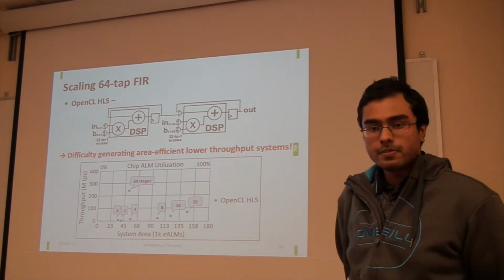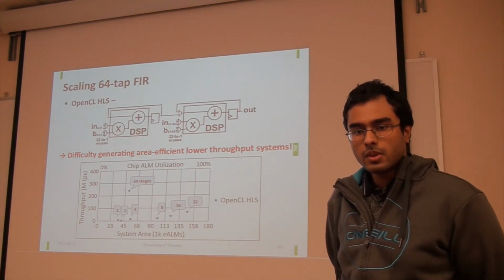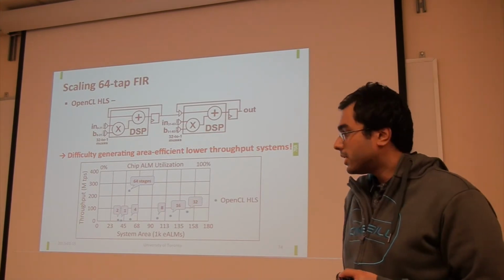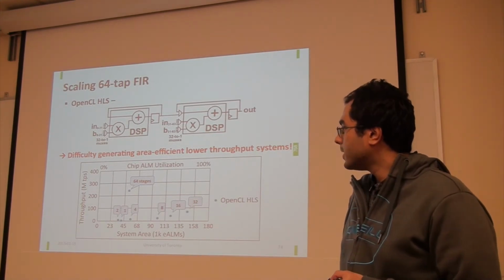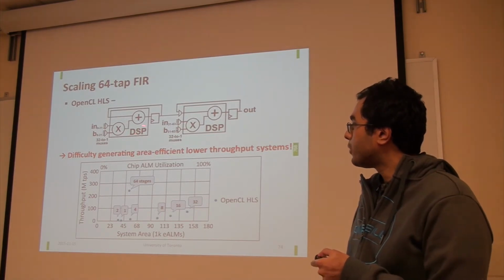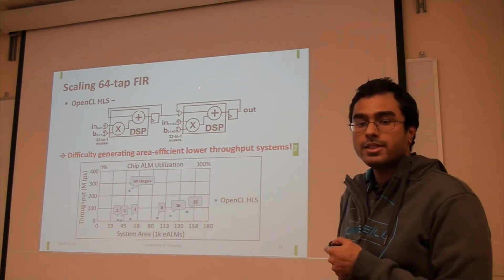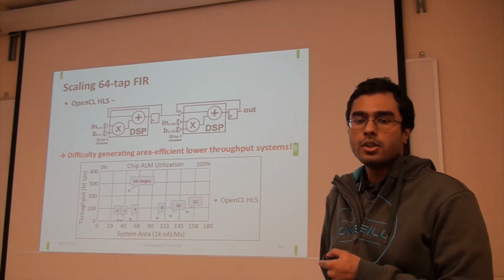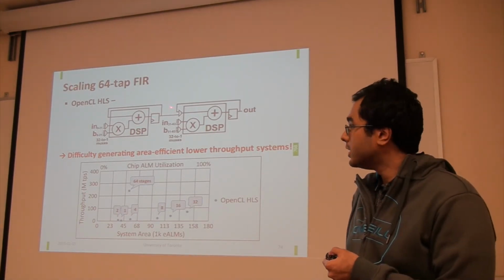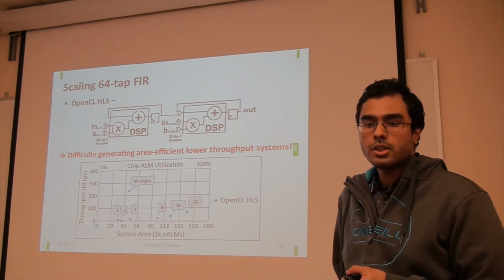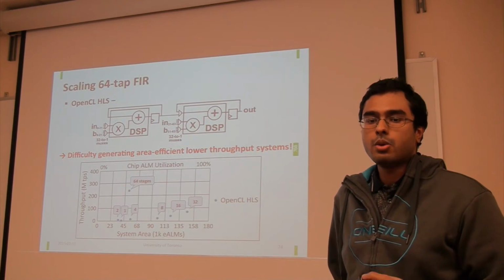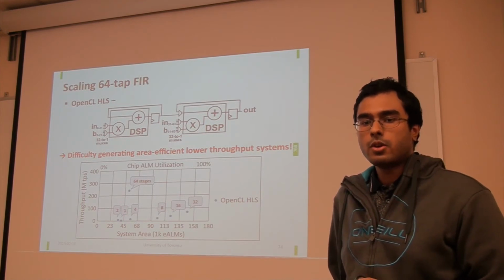So this is like the 32 tap version is 3.5 times bigger, and it's half as fast. I probably did not explain it properly, but for this example, we have 2 compute units, and it's actually performing the same 64 tap computation. So this is not an example of a 2-tap computation. The reason you need muxes in the front is because you want to select between the filter coefficients and the inputs that you want for that 64 tap computation.